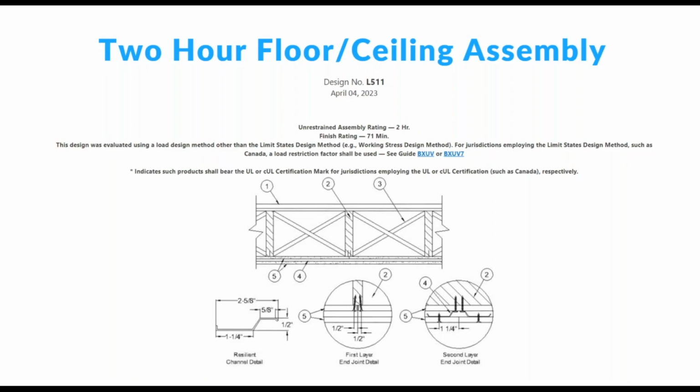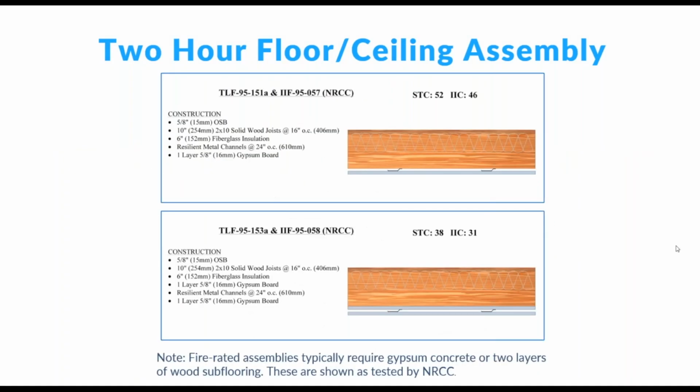2-hour assemblies tend to be different. Many of the 2-hour rated wood assemblies will have a layer or more of gypsum board attached directly to the bottom of the joist. And then resilient channel or clips and hat channel, like an air cavity, and then one or more layers of gypsum board. And you can see that here, especially in this bottom picture, right? You see this RC sandwich, is what we'll often call it. Well, that is not good acoustically.